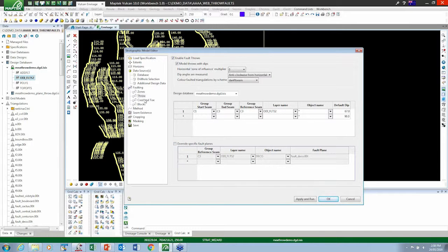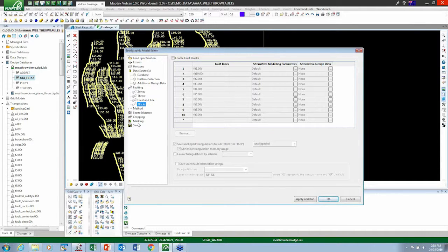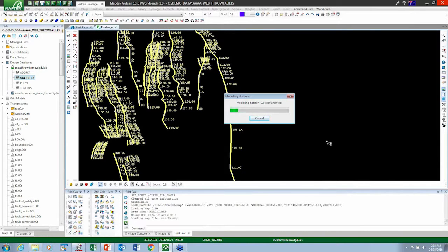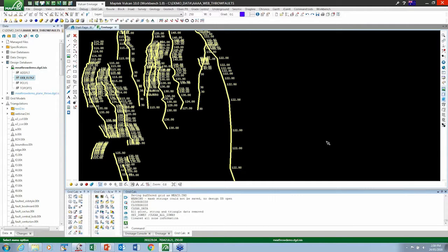So once we have that set up, all the other options are pretty much standard ISM. So we can save this. Let's pop this out into another directory, test2. Let it run. So it goes and makes the planes, and because it doesn't have to make a totally independent stratigraphic model in every little individual fault domain, it actually runs a fair bit quicker because it has to only run it once, not 30 times or whatever that might end up being.